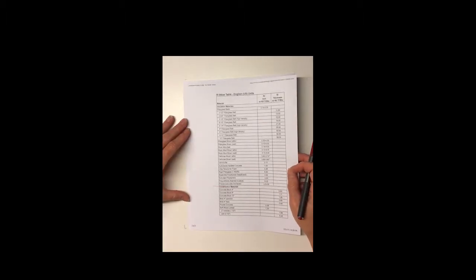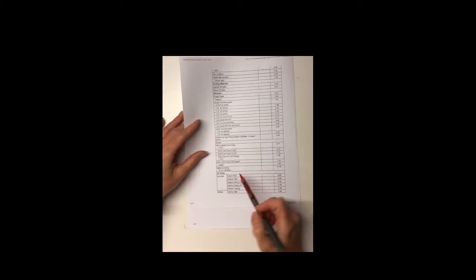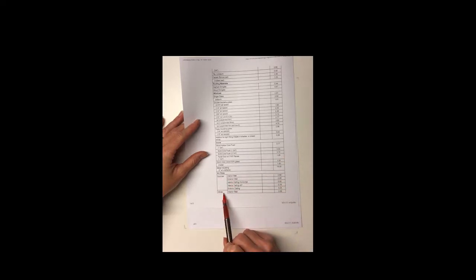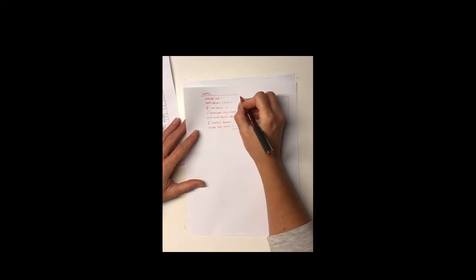And so when we're calculating the R values for those different materials, the first thing that we had was the outside air. And the outside air film, if you look at this, is broken down into summer and winter, and we're looking at heating, so we're in winter conditions. So this would be interior wall, and then the exterior wall, the R value associated with that air film is 0.17. So the first R value on the sheet is 0.17. And that would be consistent for the rim joist and the exterior wall.